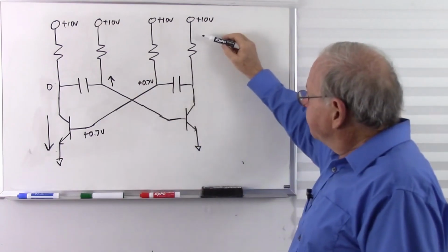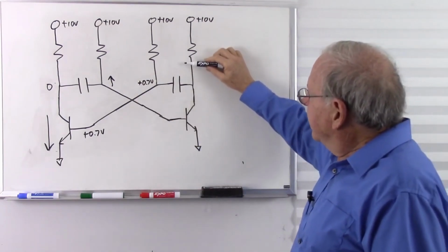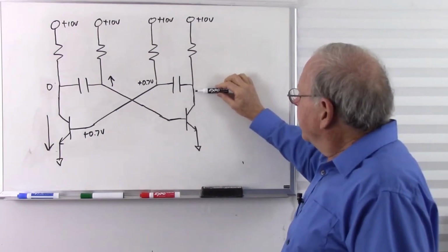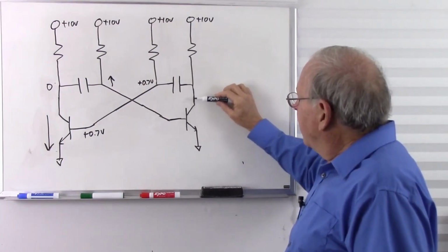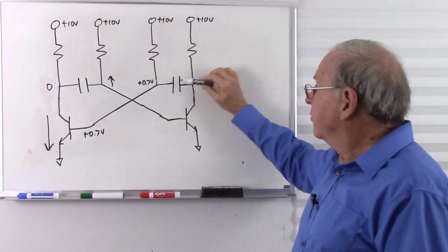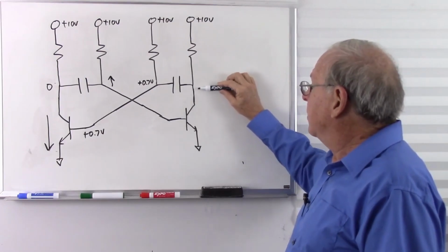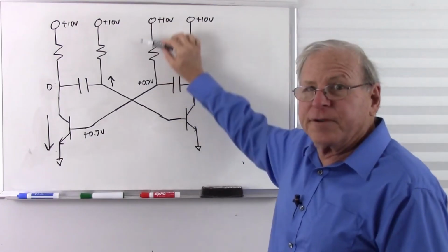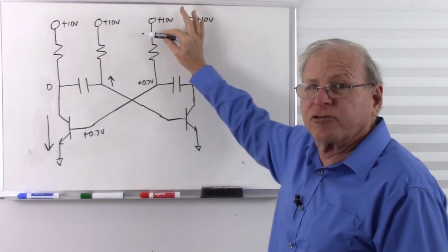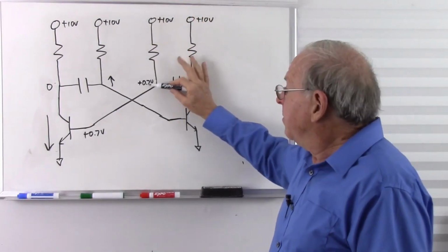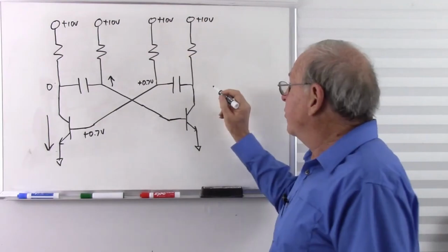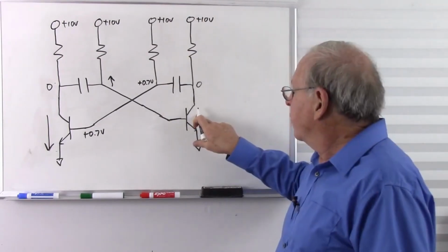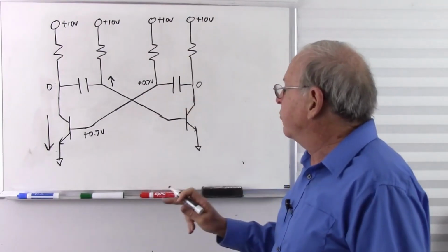And over here, with the relays, when this turned off, this jumped up to 5 volts, and then as this capacitor discharged, that climbed up to 10. And this jumped up to 15 volts, and then as the capacitor discharged, that dropped down to 10. But this never can get above 0.7 volts. So at one point just before this turned off, this was 0 volts, that was 0.7 volts.